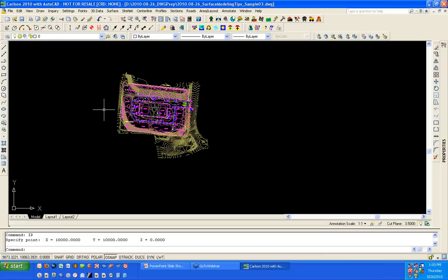Yeah, occasionally you do, so it's always good to check just to make sure, double check. You want to check 2 points. You always want to have 2 known points, and that's going to tell you if the position and the rotation is correct. Right. And you can do the same kind of IDing steps to check bearings against what you see annotated on the plat.